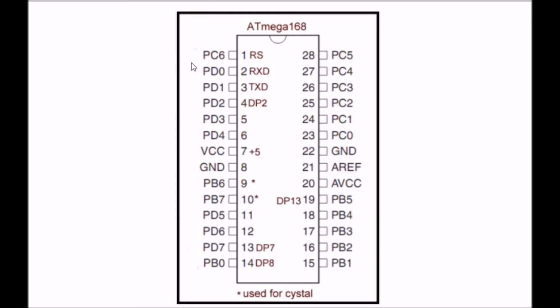It consists of ports. These are 8-bit devices, so you're going to expect these to be mostly 8-bit ports, known as I/O ports. They consist of an 8-bit latch and an 8-bit data direction register that tells the internal electronics if a particular pin is an input or an output. On this one, there are 3 ports.